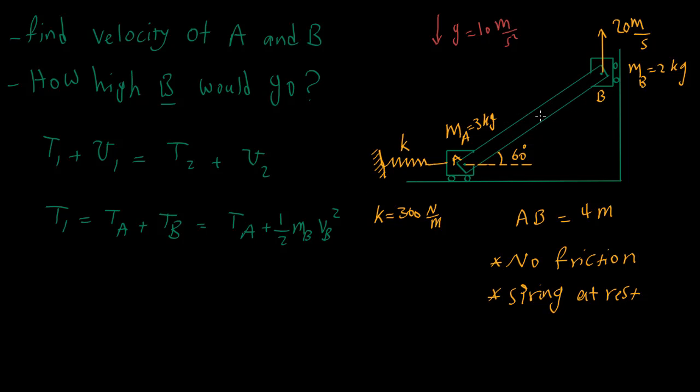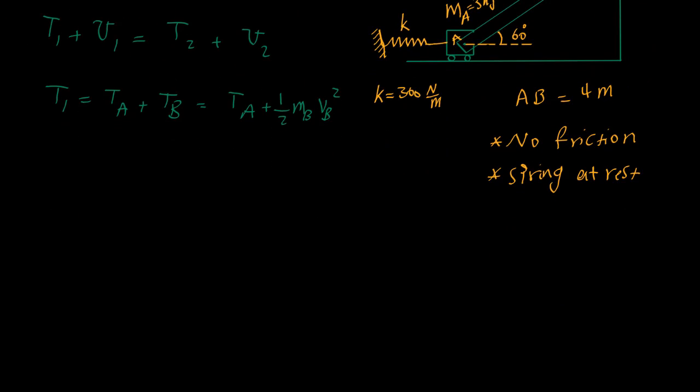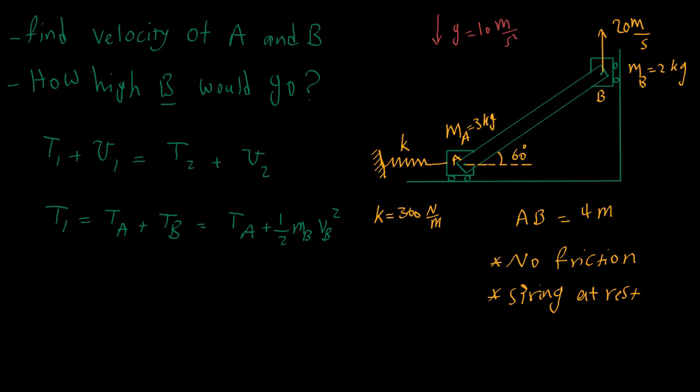Then we should be able to find omega and therefore find the velocity of A. Or I can use the concept of instantaneous center of rotation. So here, for this system, let's say this is point A, it is going in this direction, its velocity is an unknown quantity, but it is in the horizontal direction, and I know it's to the right because particle B is going upward.